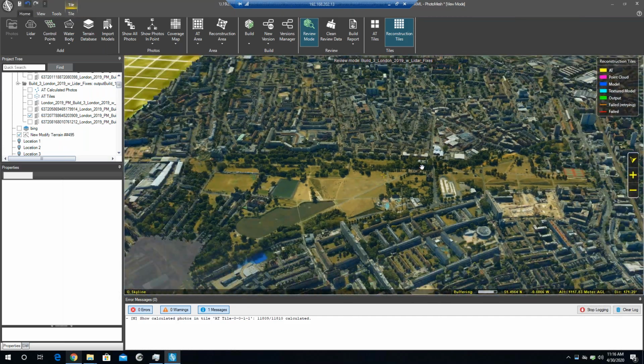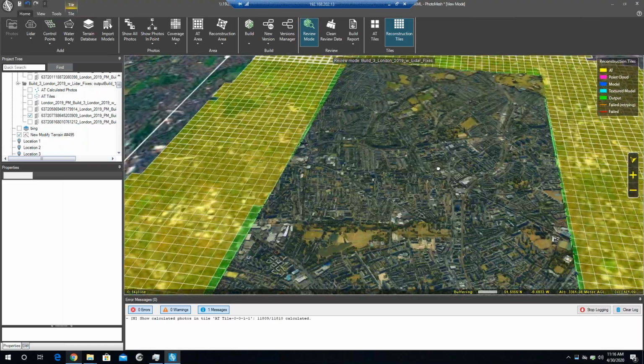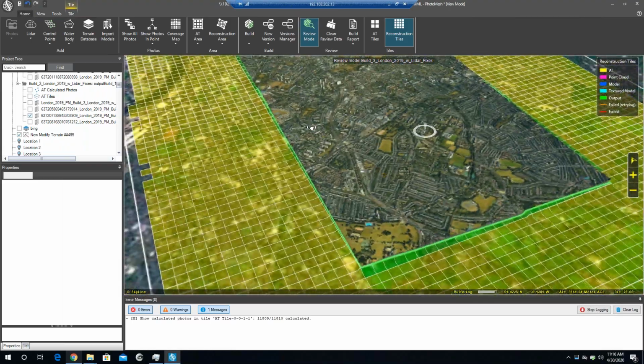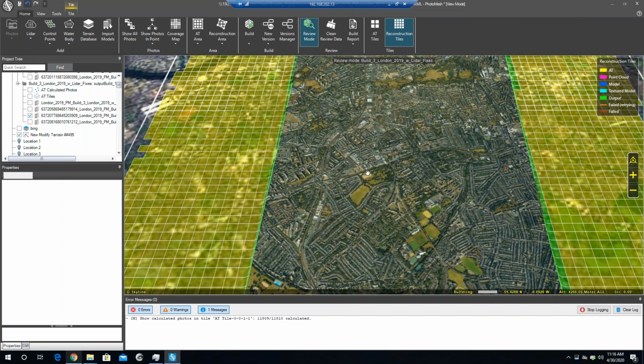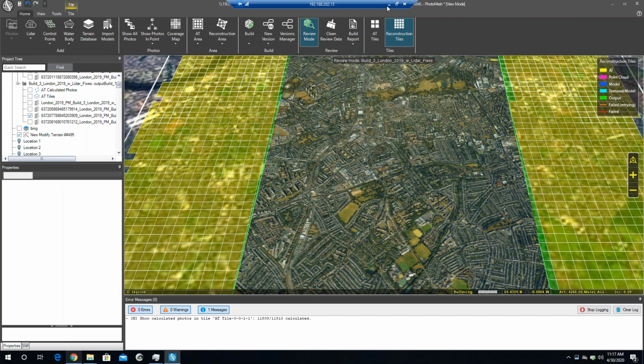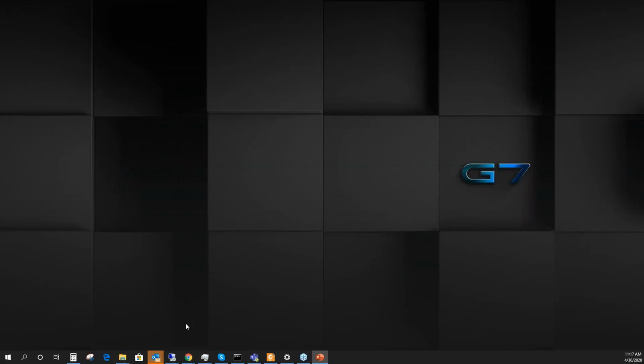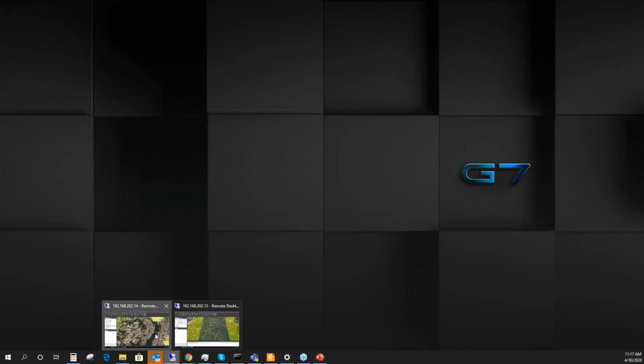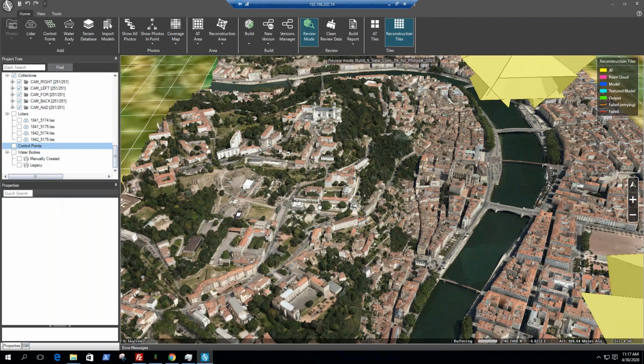So this is the complete project. Now, there's always a question of, is it 100% necessary to control the data from the LiDAR or the imagery? In some cases, if the LiDAR had control and was able to use the same controls as the images, if essentially they're both referenced to the same survey model, then it's not 100% necessary to have control.